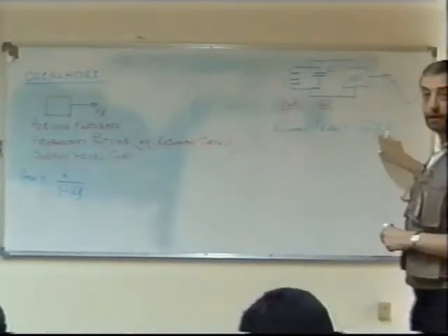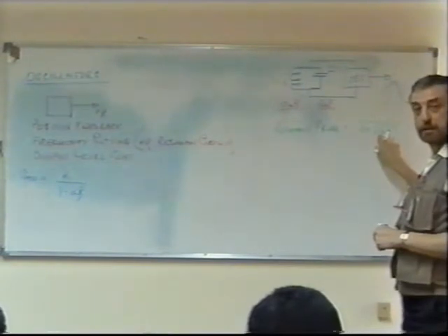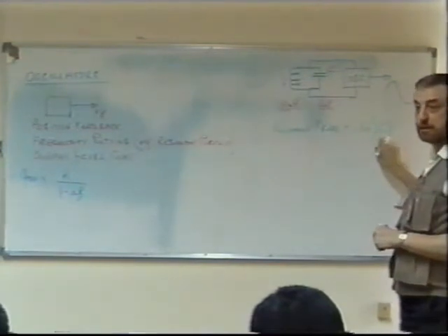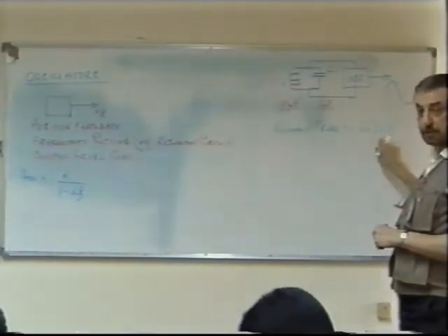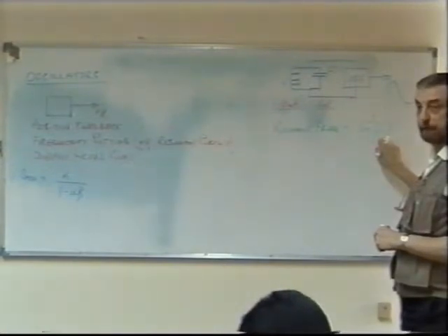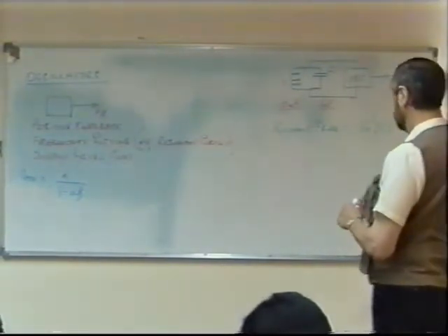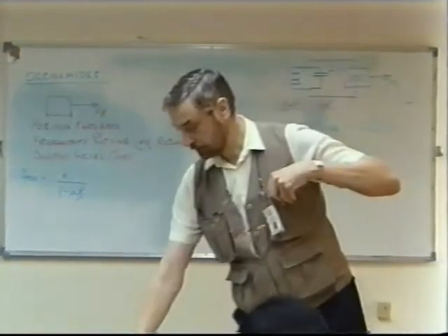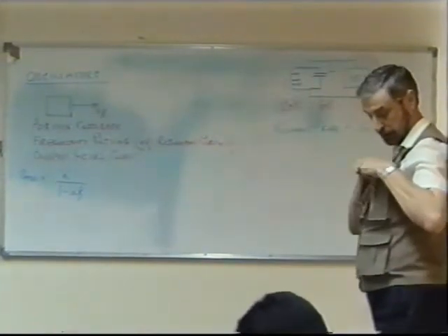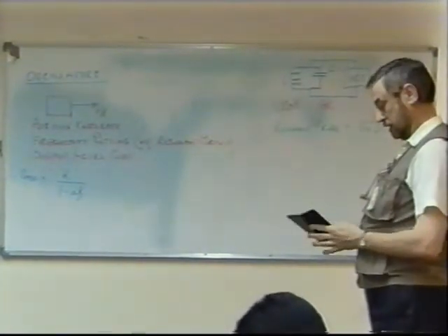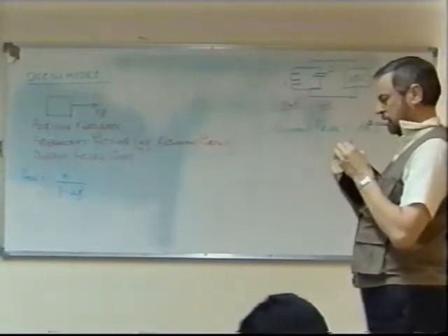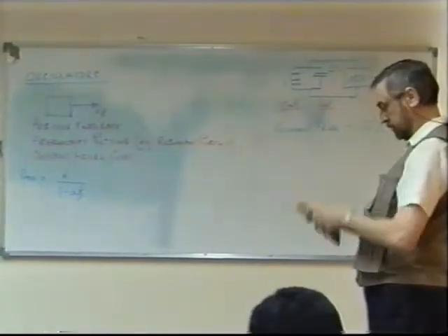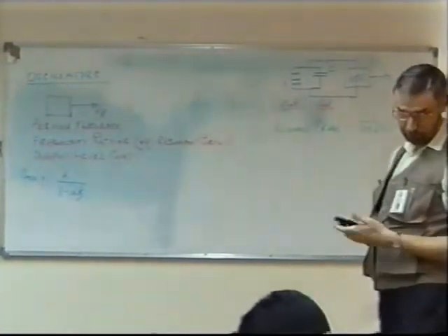So the first thing we're going to do is find out what the L times C is. Take the root, multiply by 2 pi. Reciprocal of that will give us the resonant frequency of this oscillator. Let me get my calculator out. 22.5. Keep the answer to yourself for a moment, because I want everybody to work this out. The first answer is not necessarily the correct one.